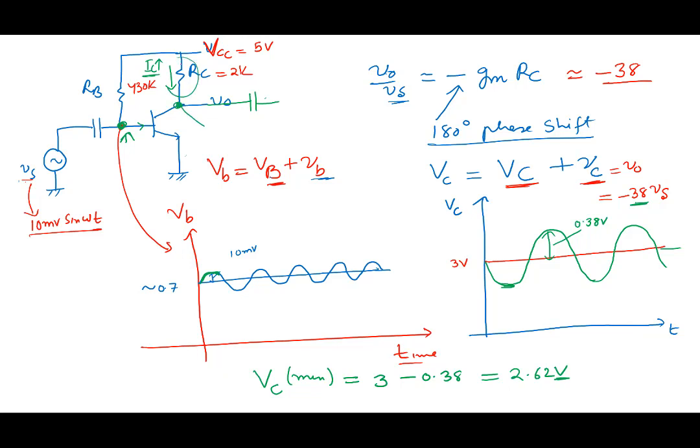The drop increases, so the voltage here, VC, goes down, and you can see the 180-degree phase shift. An increase of the voltage here causes an increase here, causes a decrease in this. That's the source of the 180-degree phase shift. So without going through the maths and minus and all of that, one can see that there is a 180-degree phase shift between the input and the output.